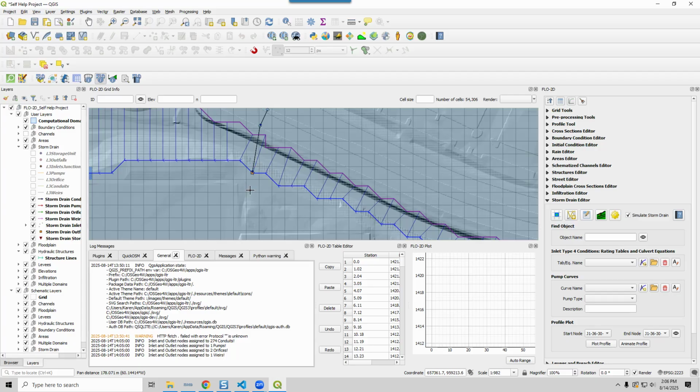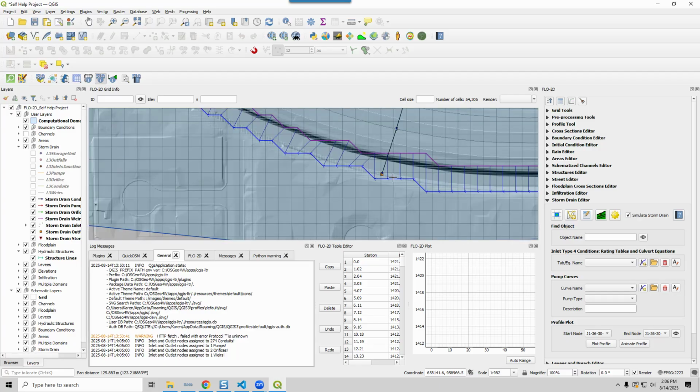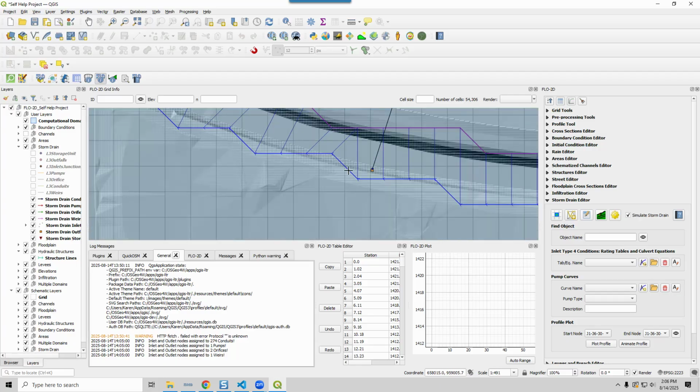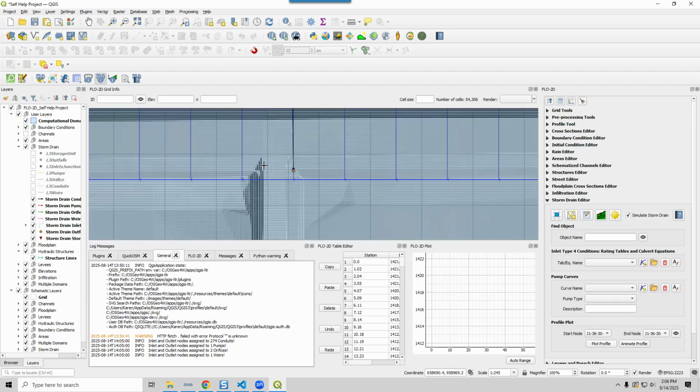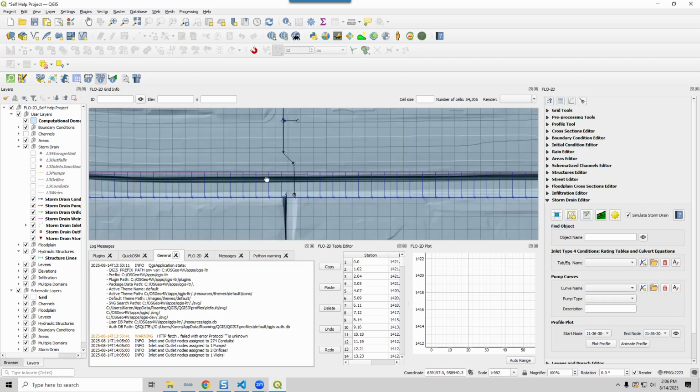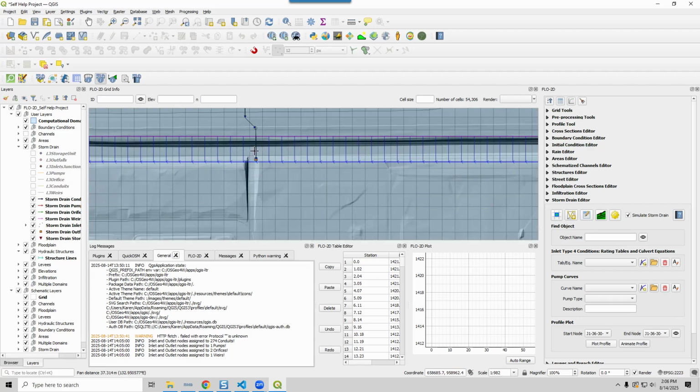Now we need our outfalls to be sort of right next to a left bank. So that means they need to be sharing a grid element with the left bank. These two are fine, even though that one's right on the boundary. It's fine because it's inside that left bank grid element. This one's fine. See, inside it, no problem there. Doesn't matter about this guy right here. That would be taken care of some other way.